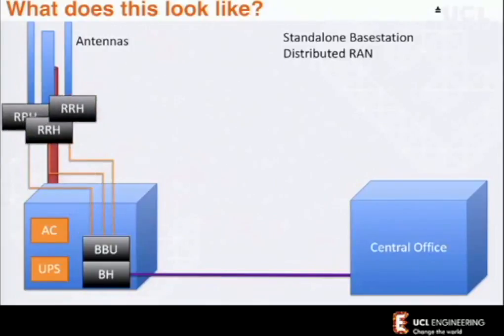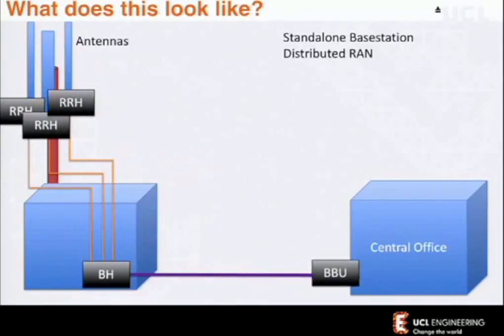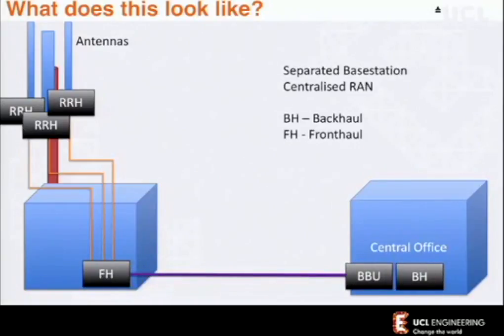So if we shift these blocks around, we can put in a much simplified front haul network: conversion from the radio signal to some backhaul signal, links over fibre, and all our baseband processing and our backhaul into the network is shared at a central site. So now we've gone from quite a large and expensive unit here to a much more highly simplified unit. Potentially even something that could sit with the remote radio head up on the top of the antenna. Maybe not even needing a separate site, although for pragmatic reasons, that's still a bit of a push in its implementation.